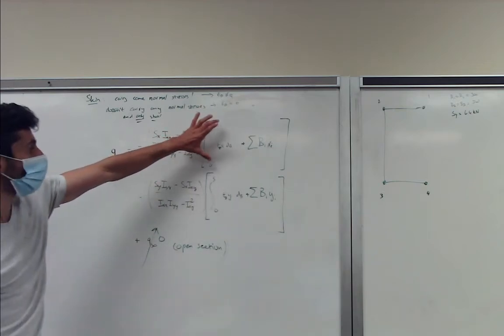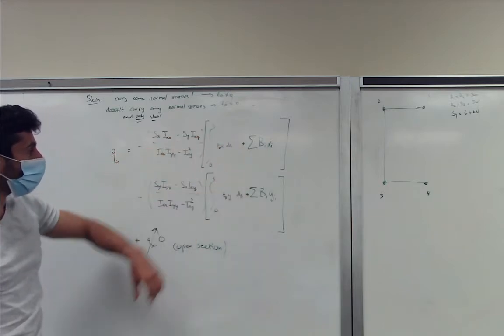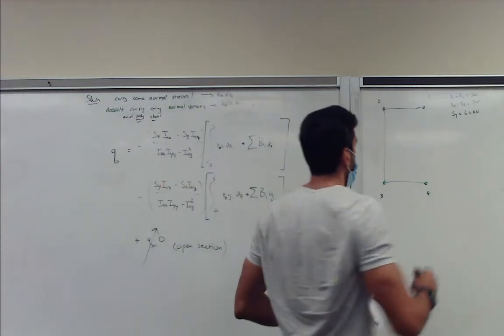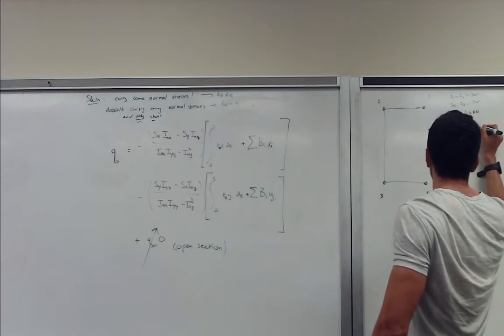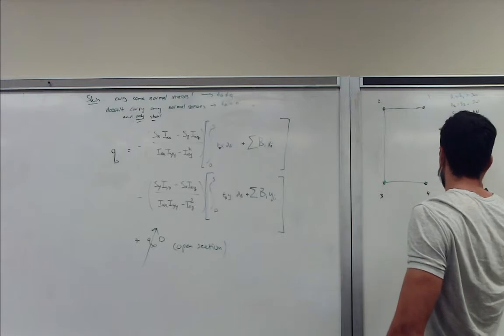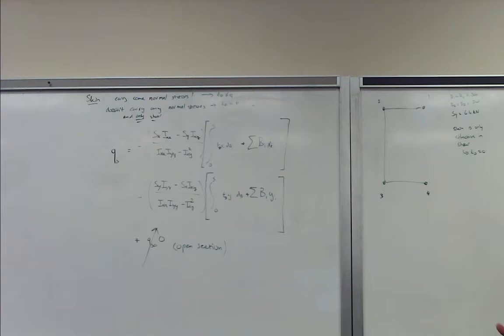So this is the direct stress component, and it will disappear based on the assumption. In this problem, the problem states skin is only effective in shear, and this would mean that tD is equal to 0, because it does not specifically talk about carrying normal stresses, therefore it's safe to assume it's equal to 0.